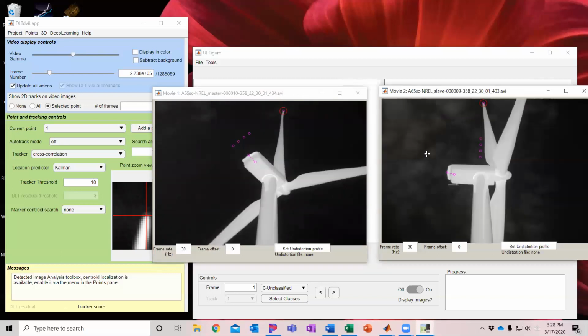And by the end of it, you should do your best to get all those 2D points. So see if you could get an orientation where you have the turbine tip up in the corner over here. And I'd recommend a total of maybe 75, 100 points to work with. I'll show you an example in a second here where we used about 65, 67 points, and that seemed to work well. But it's important that each point you digitize as accurately as possible and that that's covering the 2D and 3D space as best you can.